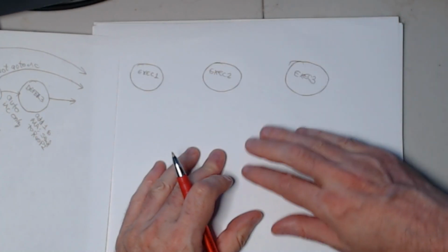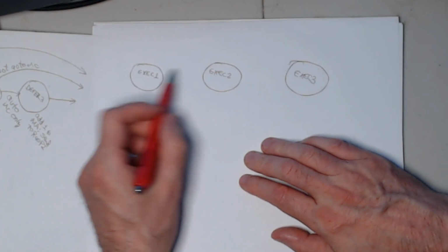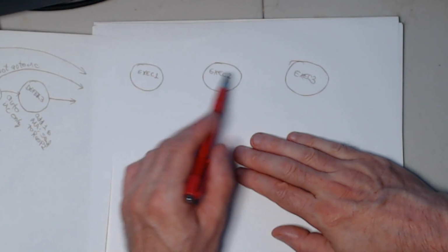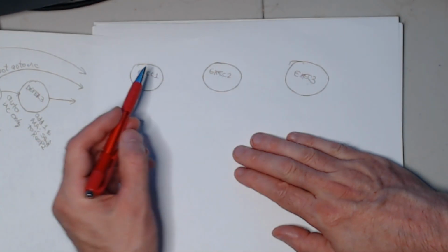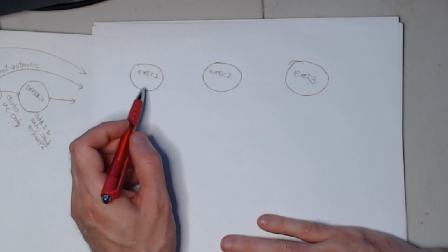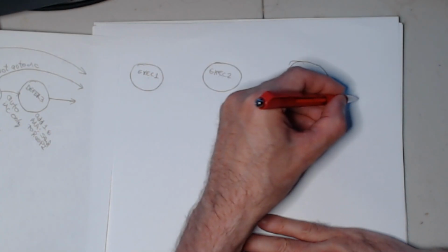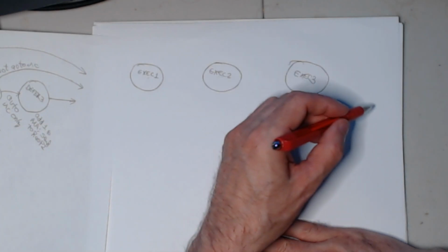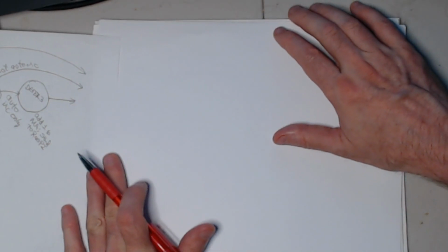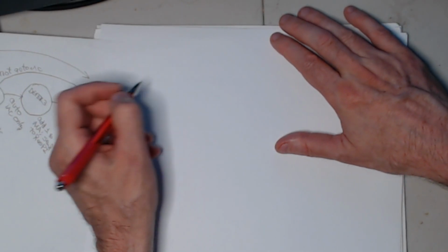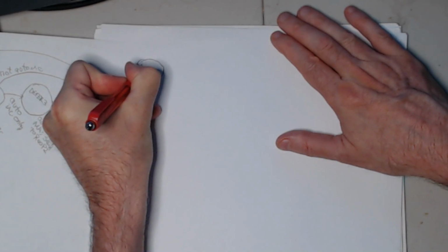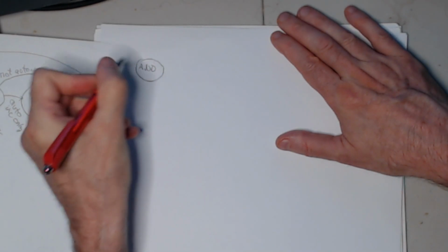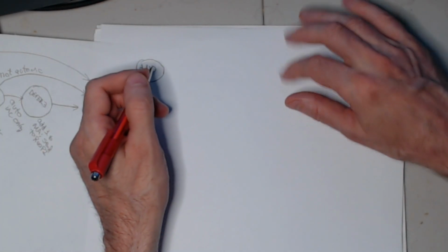Okay. Now, one way to think of these, this is how they're actually organized in the actual hardware, is there's 3 flip-flops here. But another way to think of this is there's 3 states, up to 3 states for each of the different kinds of instructions. So we can really sort of forget about this for now and break it down into, okay, so we have the AND instruction. That's the first instruction we have. And how many states does that take? AND. Okay, again, that's reading memory and updating the accumulator.